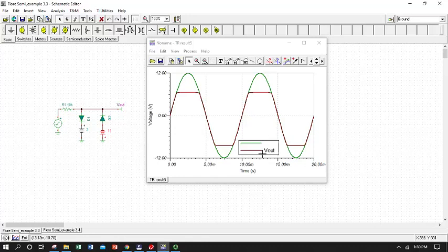So we can do a little bit of head math here, see if I can redeem myself on my video lecture. At this point I would predict my forward cycle to be clipped at V forward plus 2. So I would expect that about 2.7 would be my new plateau. So I would assume it would be clipped much lower.